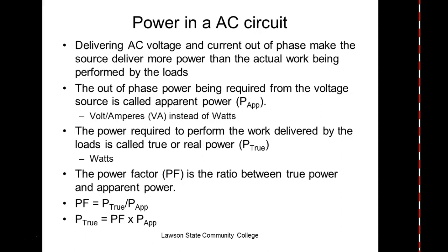But if you get to a big company, like US Steel, they have their own substation. So US Steel is responsible for their power factor. Now you would think Alabama Power would like you to have a bad power factor. But you've got to understand their whole transmission system has to support apparent power.